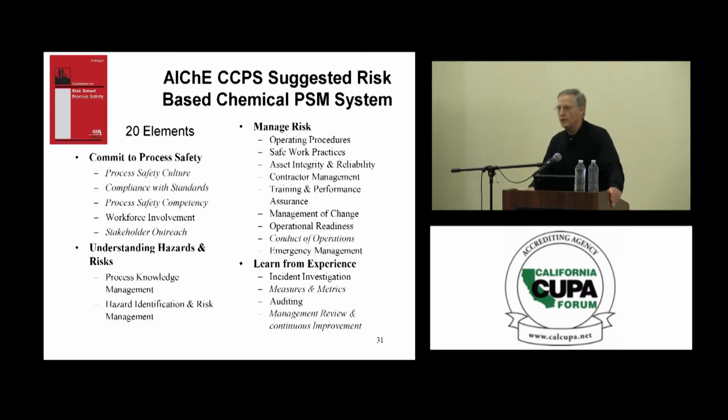I'll keep going down. Stakeholder outreach. That's not under OSHA PSM or EPA RMP. Numerous situations I'm going to describe during the day where serious accidents happened, where firefighters were killed, was because those organizations did not reach out and make certain that the firefighters understood how to respond to a situation where you have a potential BLEVE of a tank, whether it's a railroad tank car, a truck tanker, or a stationary tank. And how many of you think that BLEVEs only can occur with a propane tank or ethane or butane?